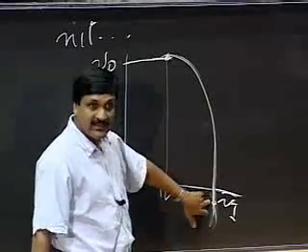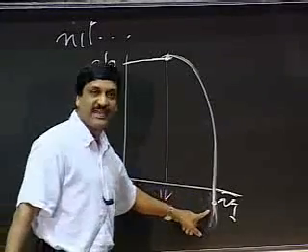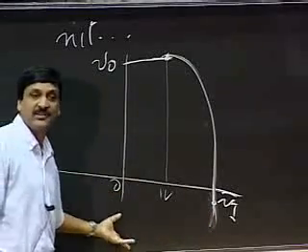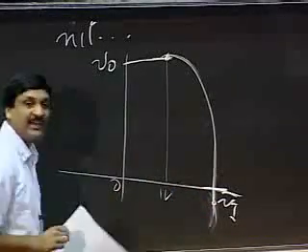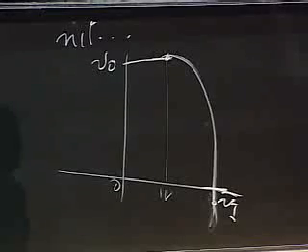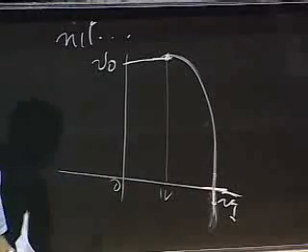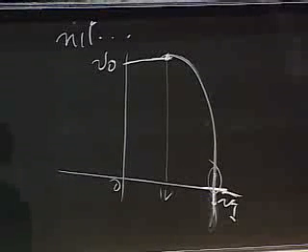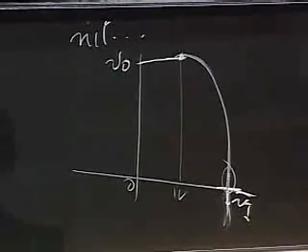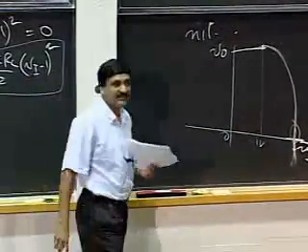Here, on the other hand, my output has gone negative, but it's still sitting there sinking current. Because V0 is negative but my current is still in the same direction, the device has begun to supply power. So mathematically, this curve says that the device has begun to supply power. It turns out in our practical device, it's a passive device, so it cannot go here. Somewhere along here, the model breaks down. The equation I've shown you for the current source, here we go, this model breaks down. When V0 becomes very small, the model breaks down and it no longer behaves like a current source.